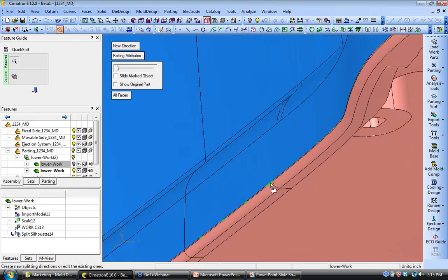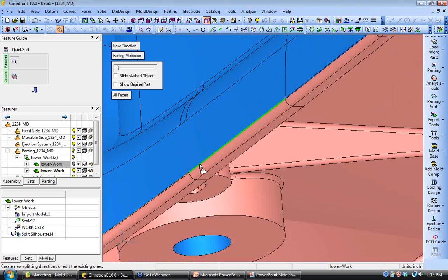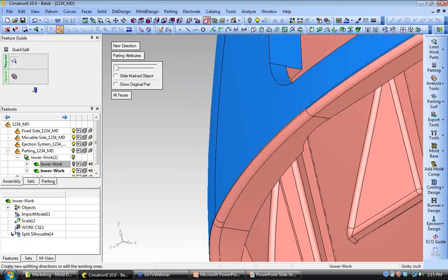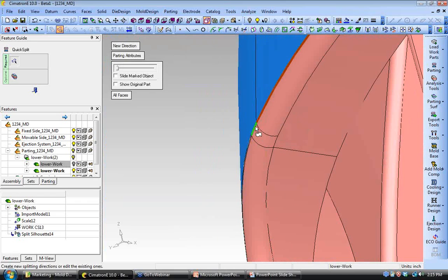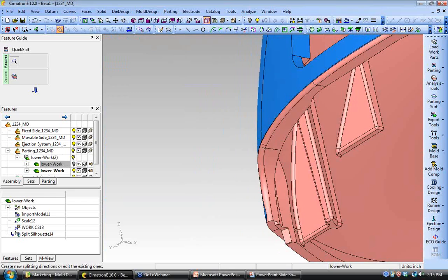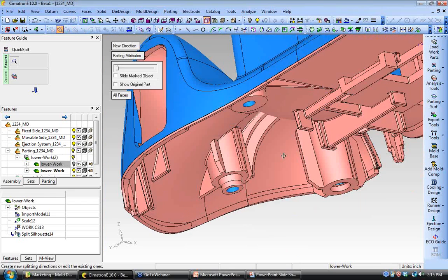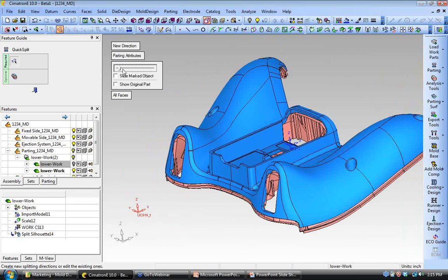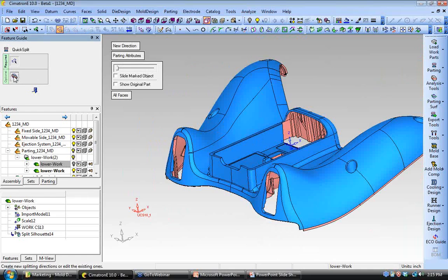One other note on the split silhouette, which is a very nice command. With the split silhouette, you can also enter in a value for 7 degrees, so it will split it from the horizontal up or down 7 degrees. You know, if you have to have grain or texture in the mold, you can automatically get that line, instead of at the silhouette, up 7 degrees.